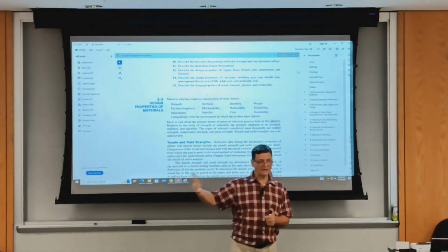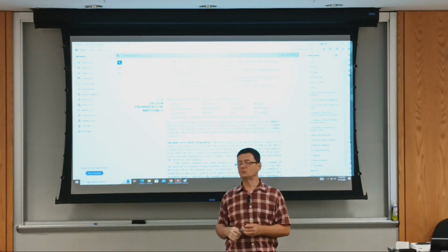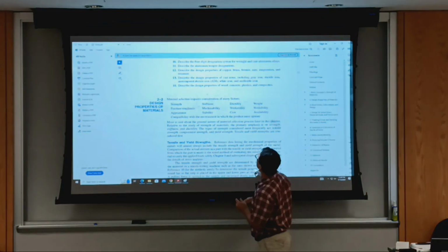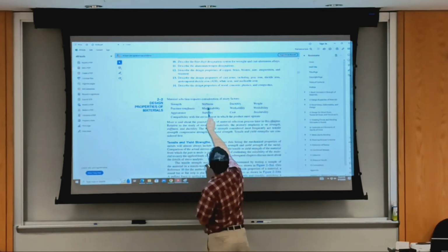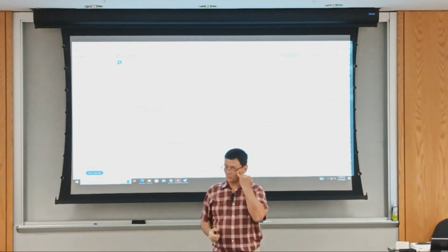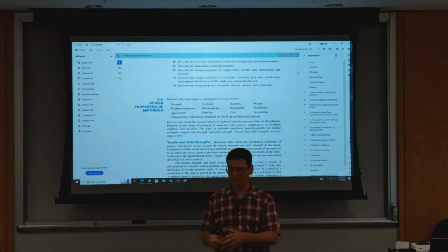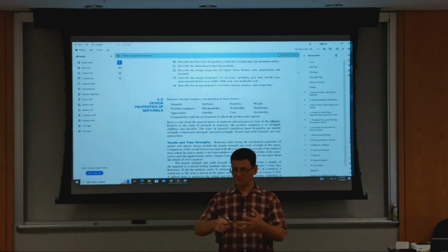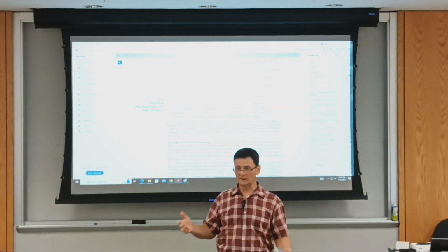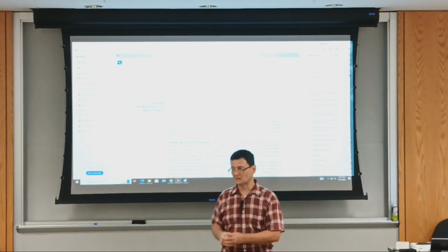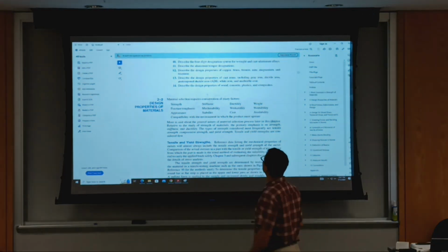Machinability. Sometimes you sacrifice, you'll learn this in manufacturing processes, maybe you've been told in material science. So you sacrifice properties like strength or ductility to make it more machinable. For example, if you machine it on an automatic milling machine or an automatic lathe, and the chips are continuous and long, that's a problem, because you need an operator to pull them off, or they get entangled and break the spindle and stuff like that. So you like short chips that break by themselves and can be washed away.